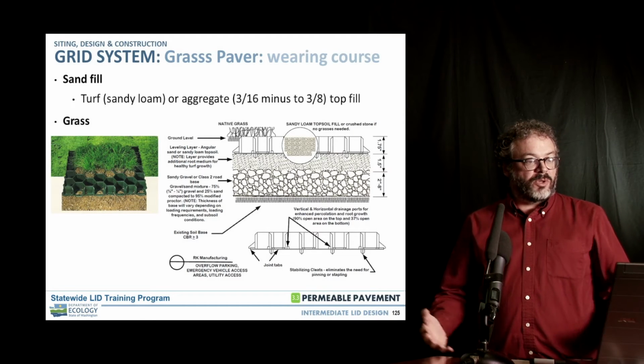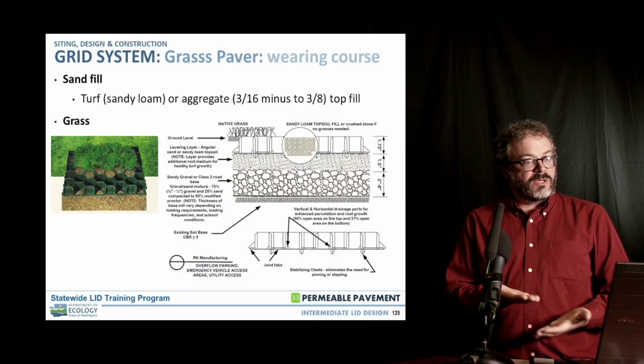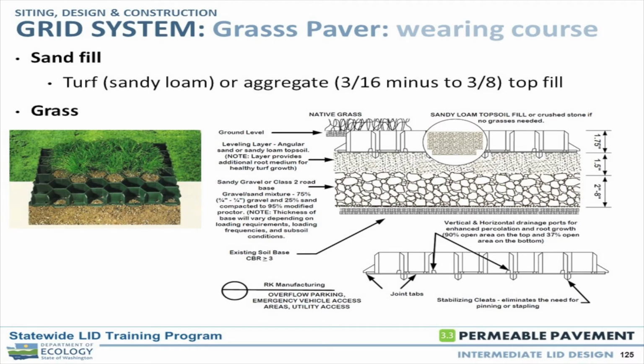So we mentioned earlier that the fill material in the grass application is a nice sandy loam. For the grass paving, the soil that I use is essentially bioretention soil mix, 60-40 blend, amended with this moisture holding admixture amendment, and that's essentially the mix that I've used, and that seemed to work really well.